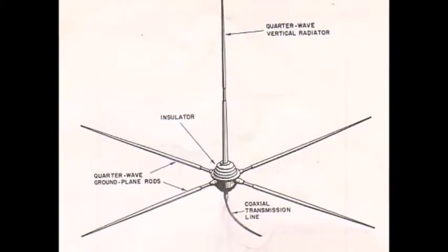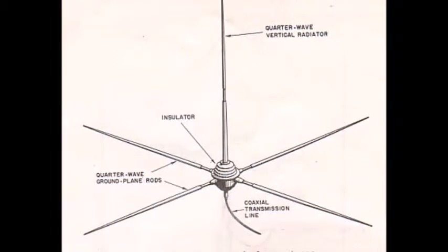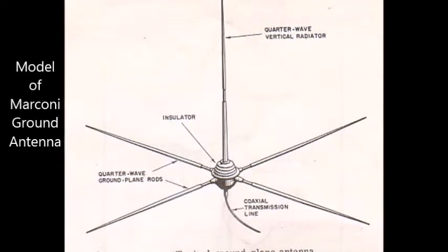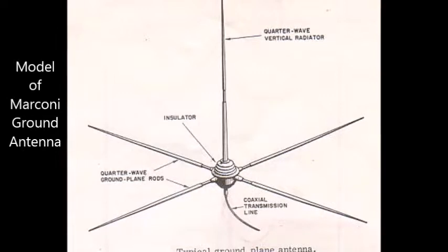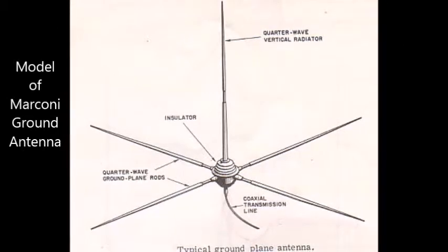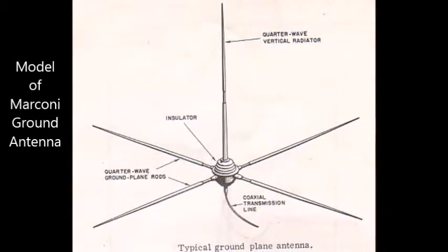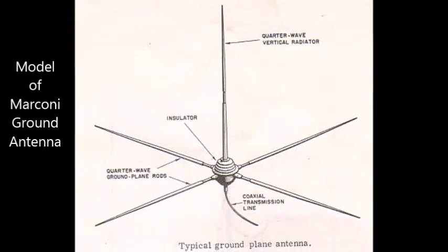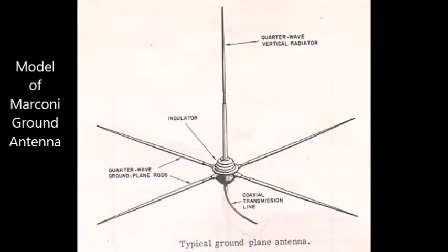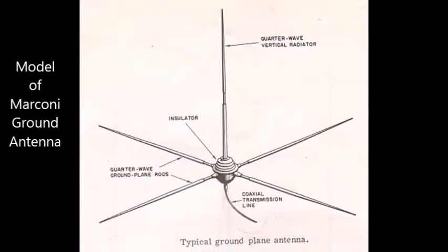In theory, an antenna's resonance is made up of a magnetic field brought by an inductor and an electric field brought by a capacitor. In general, the larger the antenna, the lower the resonant frequency will be. It should also be noted that if the antenna being tested is exactly half the wavelength, then the equivalent circuit will resonate.